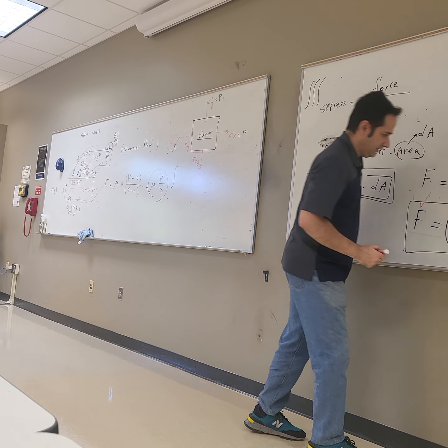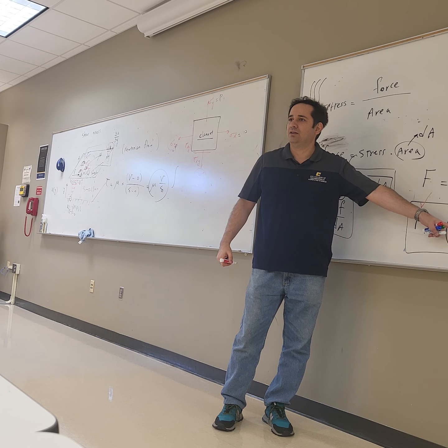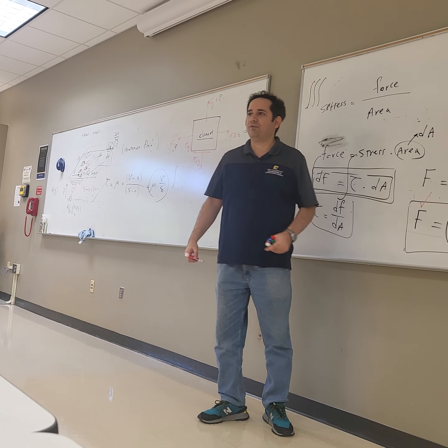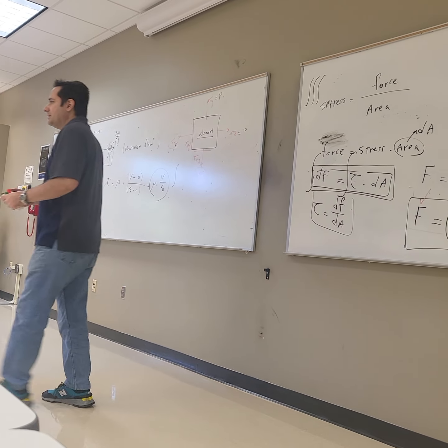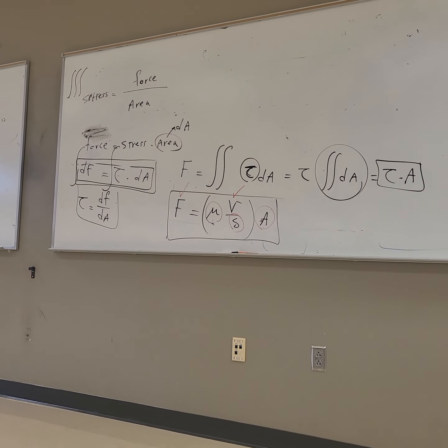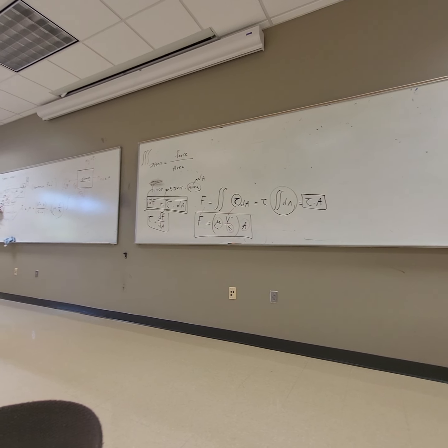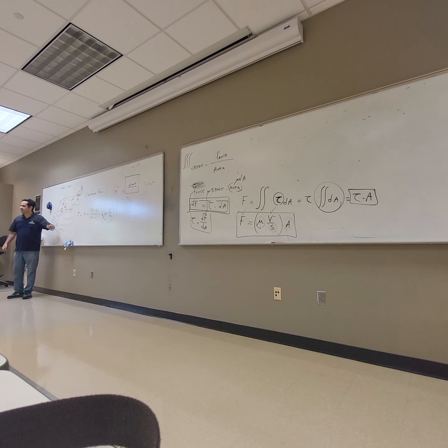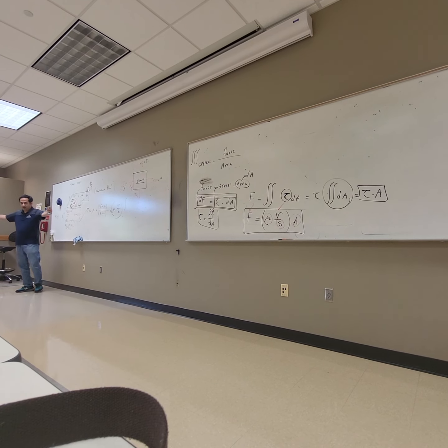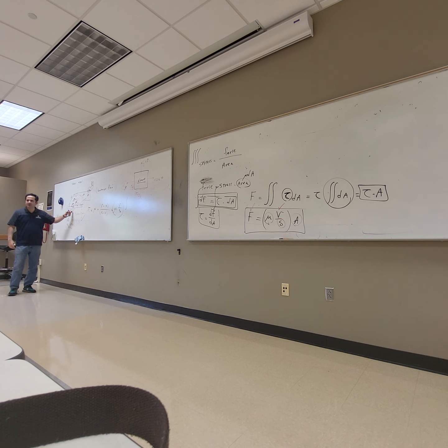of the metal sheet. So what do you need? The only remaining thing is viscosity. You can compute it. So in fact, you can compute the viscosity in the lab using the same experimental setup. But look, for that, you need to make a huge metal sheet, and it's not accurate. Why? You see that the distance is not always going to be 0.1 millimeters. Sometimes, because the sheet is big, in the middle you have twists or it goes up and down. So this is not a good way of measuring that. There's another way to do that.